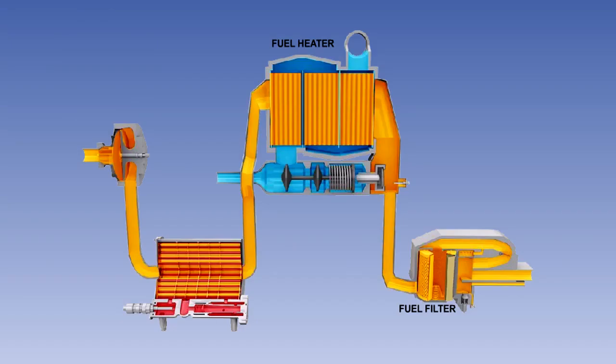As a further precaution, in order to prevent any ice crystals blocking fuel filters and jets, the fuel may be passed through a fuel heater located on the engine, which uses hot air from the engine compressor to remove any ice crystals which may have formed in the fuel when it's cooler than 0 degrees Celsius.